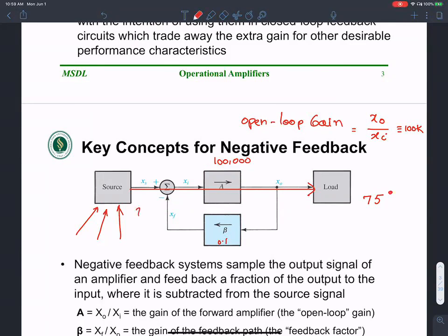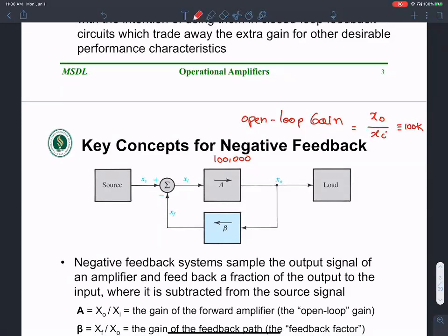In order to know when to stop, we have to feed the status of the output back into the input in terms of an error signal here. So that's the idea in control systems, in systems where we have to read the output in order to control the input. A feedback configuration is used. So we begin with a really large open loop gain. The op-amp is said to have a large open loop gain. We design it so that it has a large open loop gain, 10K.